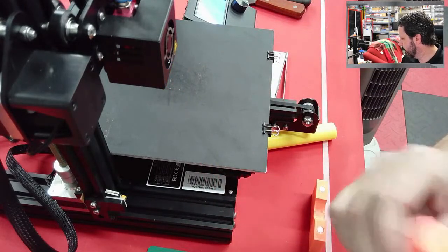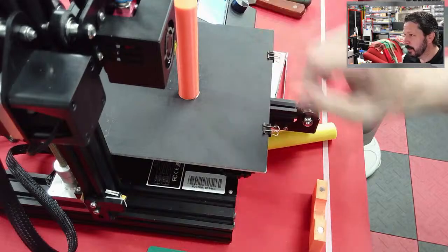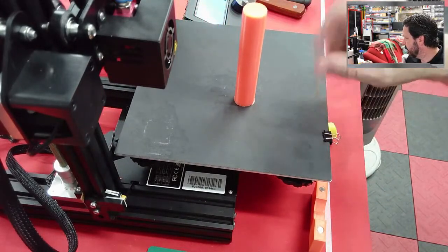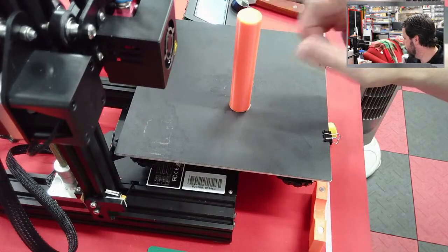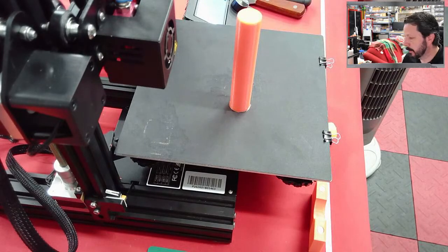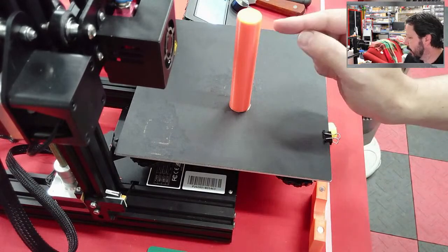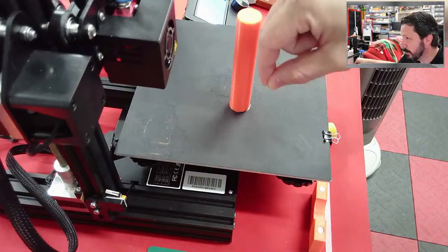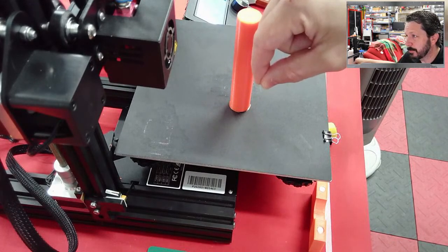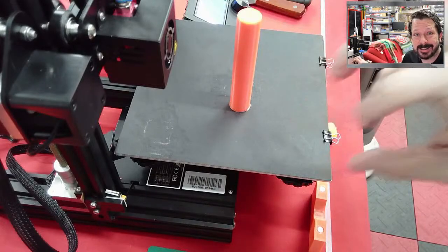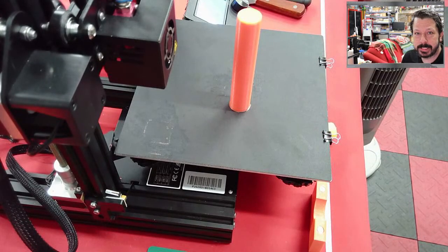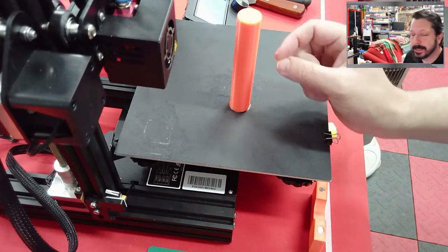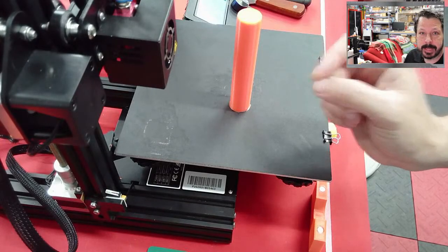This is not going to affect this one, but here, if you had a part that was very skinny, so much skinnier than this, like came to a peak, like a pyramid at the top, then there's a really good chance that that top part is going to be all deformed. Because when the printer is printing those very top layers, if it's just a peak, it's just going to make a little circle, then move up, print a little circle, move up, and the hot nozzle never gets very far away from the material underneath it to let it cool down. And so the tops of really spiky things tend to be kind of deformed.